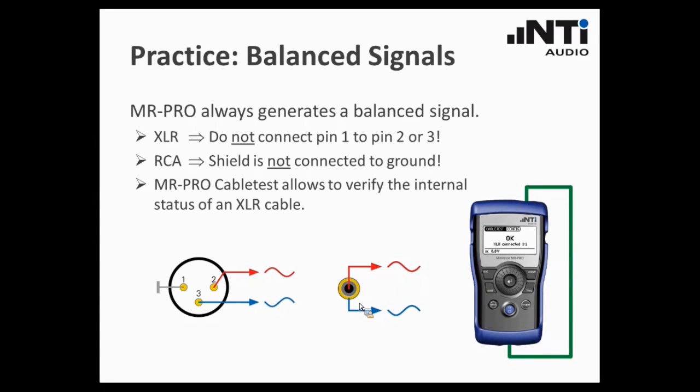One more hint, a side note actually, because we're talking here about balanced signals, and of course you can also have some problems or issues if the XLR cable that you connect is not properly connected internally. You can verify that with the cable test that is provided by the MR-PRO. I'm going to show that to you as well.